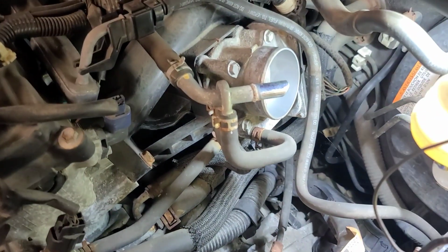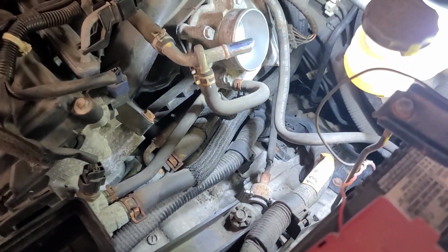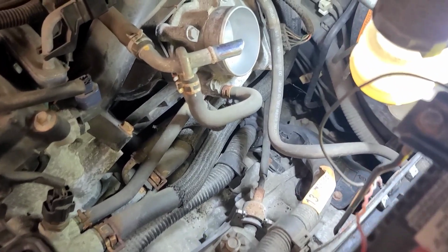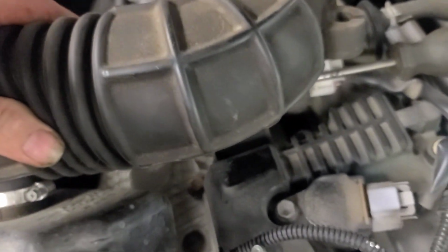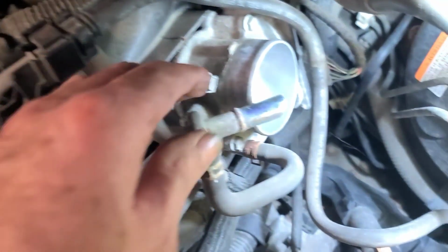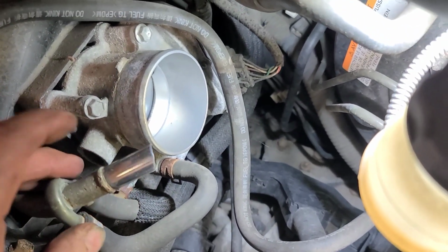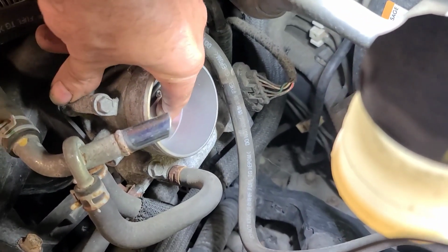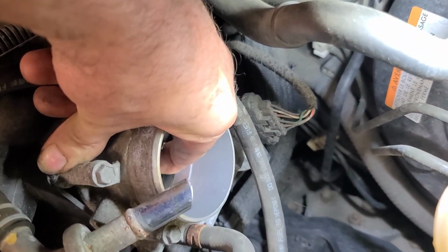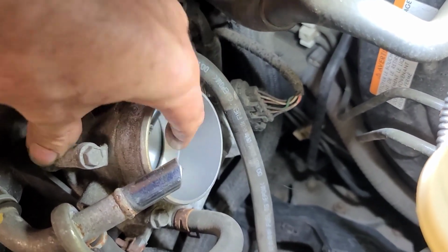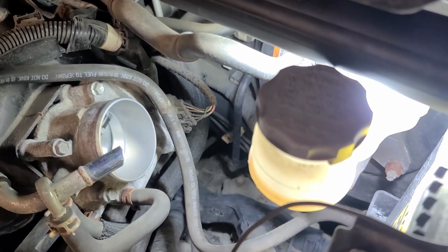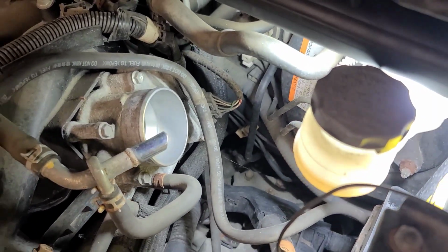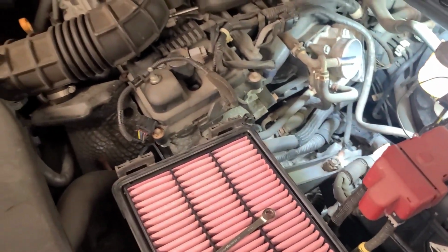So there's the air induction off. As I said, the air filter is not that bad. So I don't think that's an issue. There's a hose clamp here, a hose clamp here. Like I said, I've checked the bellows for a tear, and there's a small PCV fresh air inlet hose here. See, it's liquid heated. And looking at the throttle body, it doesn't look that bad, but we're going to clean it. Can't even see in there. Use some combustion chamber throttle body cleaner and a toothbrush. And we're going to blow off the mass airflow sensor too.